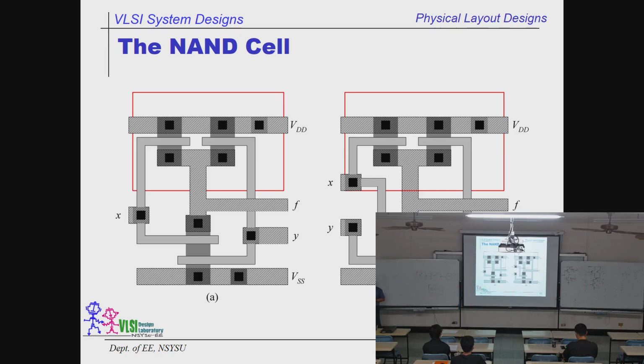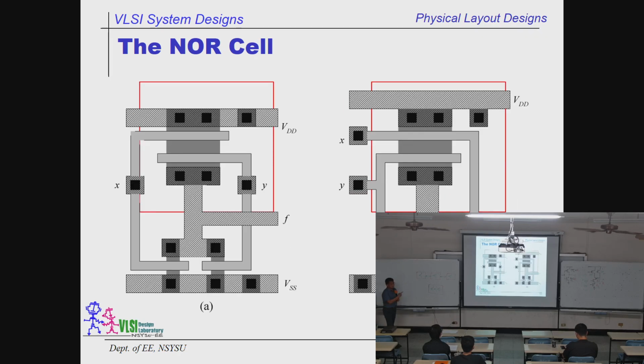All right. Okay, we are going to see a lot more examples. And what is this? This is a NOR gate. See that? We have two parallel transistors at the bottom, and we have cascaded PMOS on the top. So based on that rule, we would like to equalize the current sinking capability.